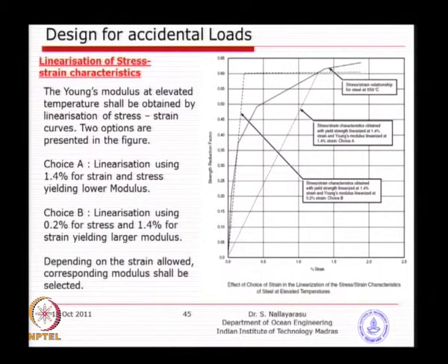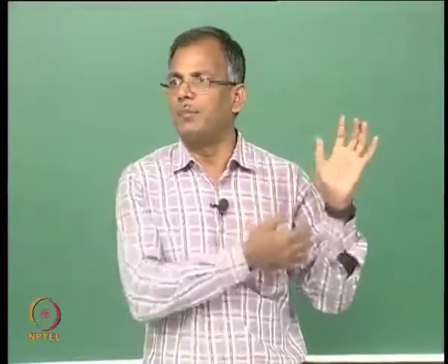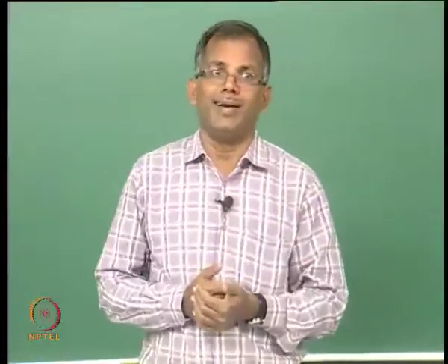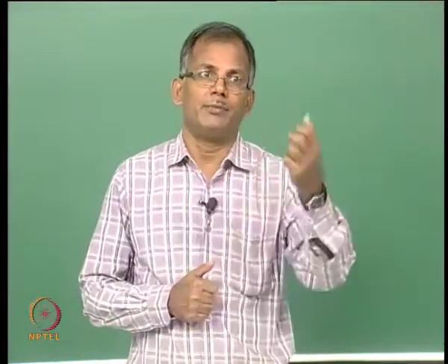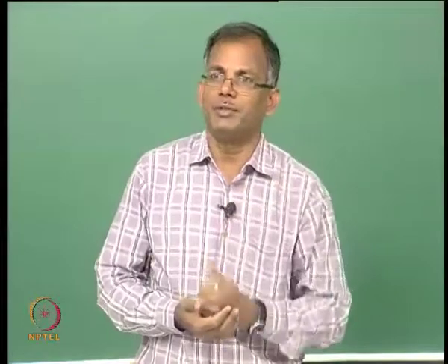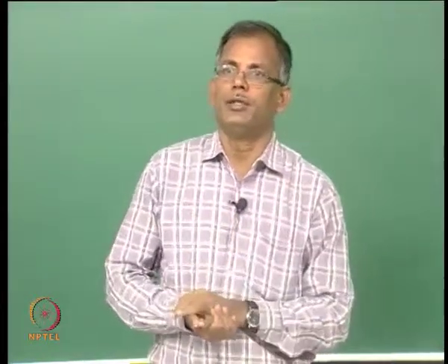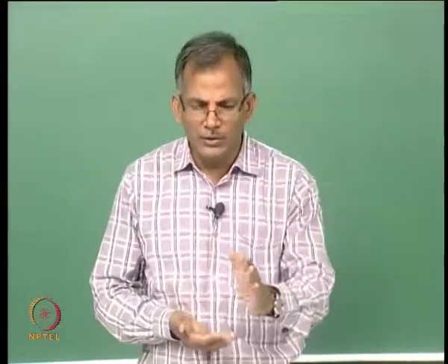Now, you see it is continuously changing, it does not follow a typical linear elastic and then perfectly plastic behavior, it is basically a continuous nonlinear profile. Now, we need a modulus of elasticity value for design purposes. When you do an analysis, you need stiffness, and for calculating stiffness you surely need the modulus of elasticity value. So, which value will we take?